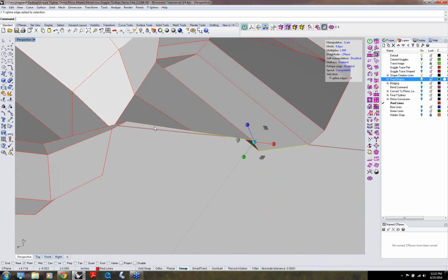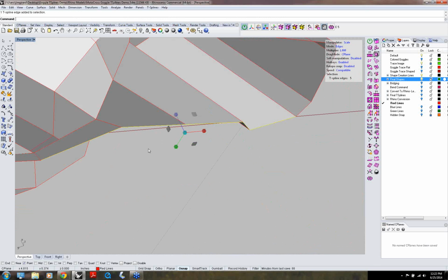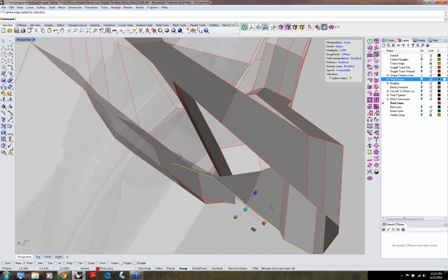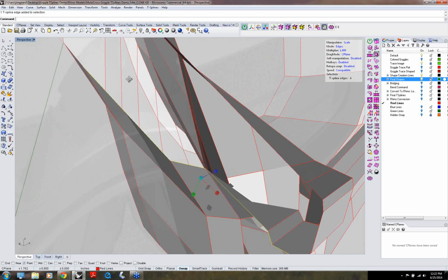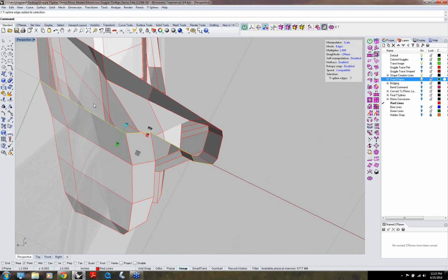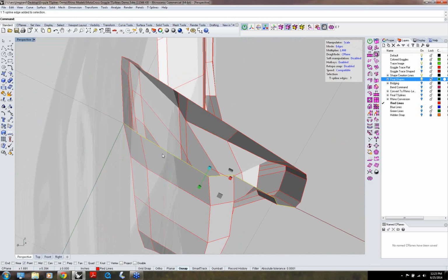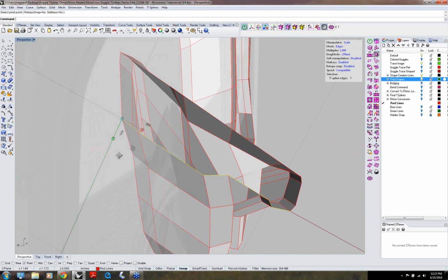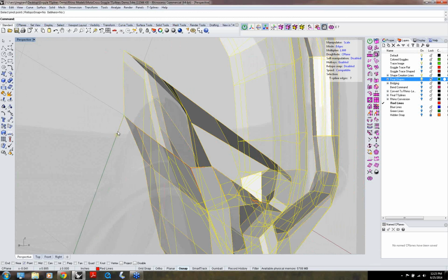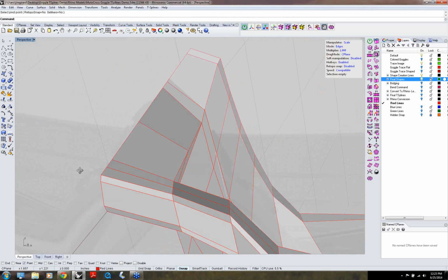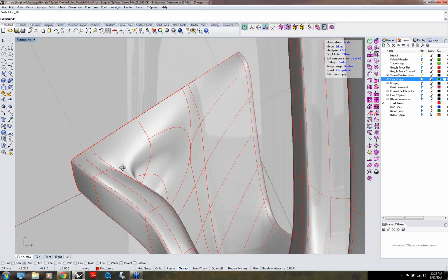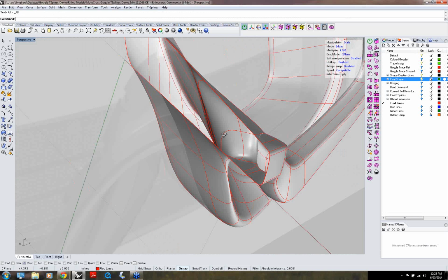And I find that for me, when I work in T-Splines specifically, if I can keep an orderly model and really understand what all the edges are doing, it's a much cleaner and higher fidelity model than I've ever had. So then I go back and I pick the point where I want my manipulator, and again, pull those points into line. Now then, when I hit tab, you'll see that I have a very clean bridge.